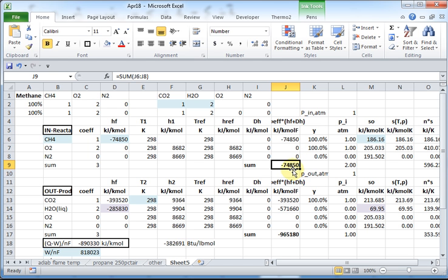That's in the energy. Likewise, CO2 going out, we type in its enthalpy of formation, and we know the stoichiometric coefficient, and there's no delta H. Delta H is 0, so we get the coefficient times H of F for the CO2. You do the same thing for H2O, but notice it's liquid, so I need to put in a liquid's enthalpy of formation,